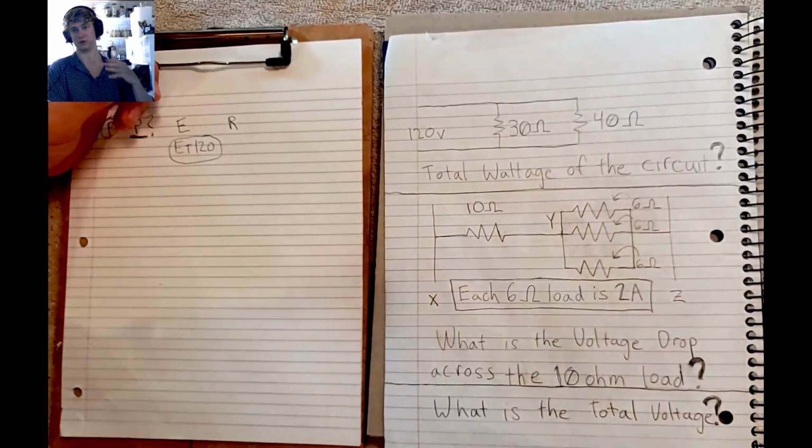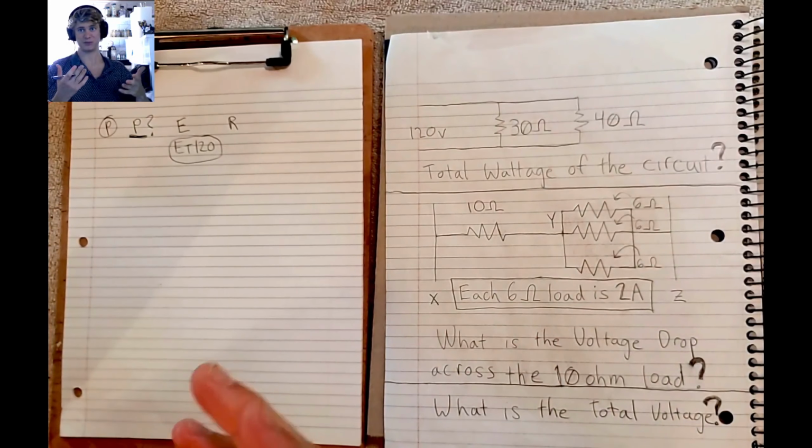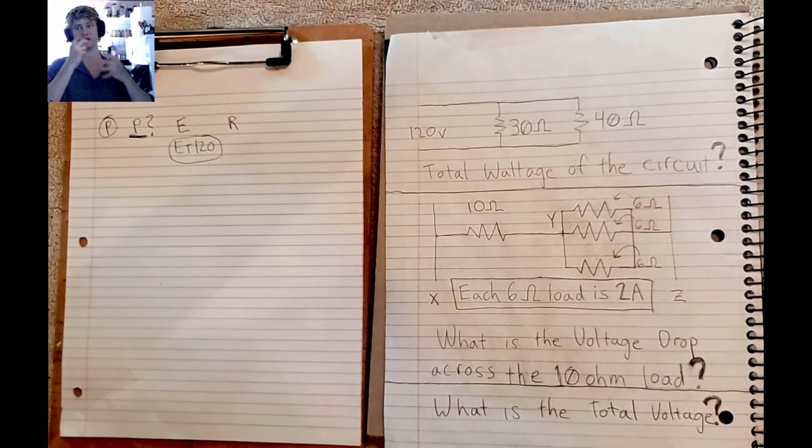In a series circuit, since they add together, your total resistance is always going to, of course, be a bigger number than your individual resistances on your resistors. However, in a parallel circuit, since you do the weird thing known as the reciprocal, which you do 1 over each of the resistances, and then you take the reciprocal of that by doing 1 over the total of all that, in fact, now you will actually have a smaller total resistance than you will have on each of your separate resistors.